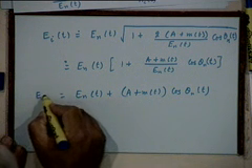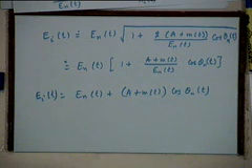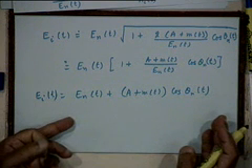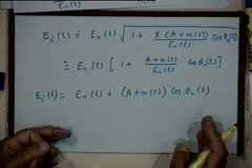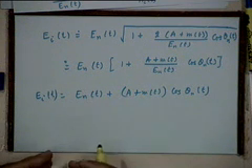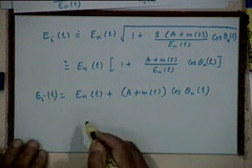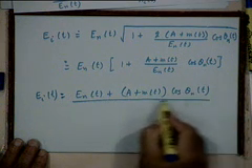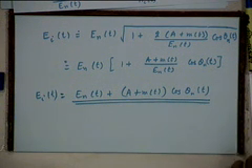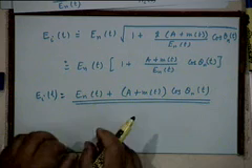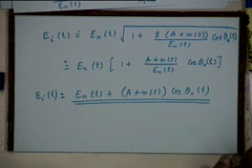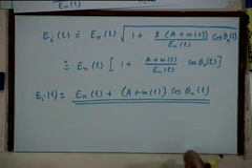Your instantaneous envelope is this, which means your envelope detector will produce this kind of an output, right. Whereas, what is it that you would like to see? You would like to see something proportional to Mt. Unfortunately, in this expression you do not find any term which is a constant times Mt, right. It is not even that you have something constant times Mt plus something. The plus something we could have considered as noise, and you would have a signal term, and you would have a noise term, and you would have calculated a signal to noise ratio.